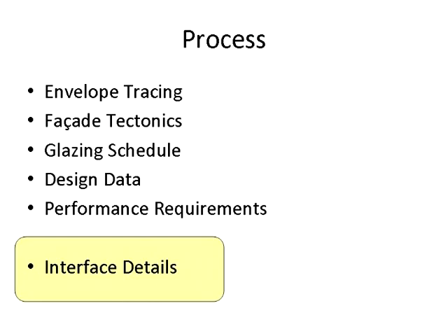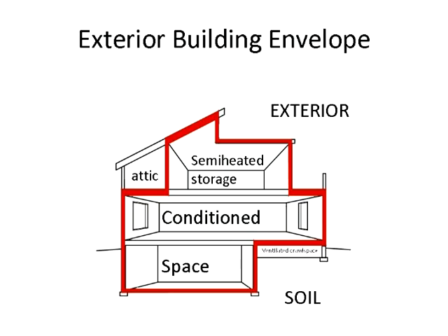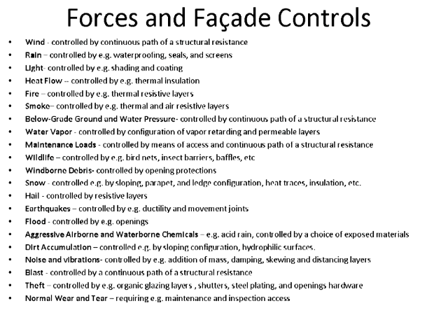Again, we cannot hit a target that we don't see, and therefore in all plans and sections we have to trace the building envelope, which separates mechanically controlled from uncontrolled environments. You may need to draw a separate line of enclosure which would separate the dry from wet zones. There is a law of continuity. It says that whatever facade function you analyze and whatever building section, no matter horizontal or vertical or what scale you analyze, you should be able to trace all the functions continuously without any interruptions or offsets.